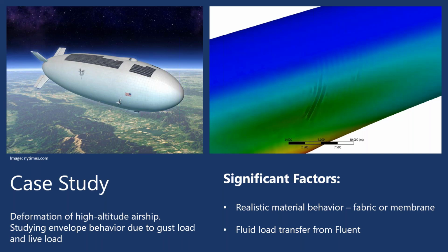And what we found was that, under the weight of the keel that is supported by that envelope and due to typical sagging behavior, that does create some rippling or ruffling of the material that also changes the aerodynamic properties of that ship as well. And really that would have been something difficult to do in any sort of implicit study, emulating that material behavior that realistically.